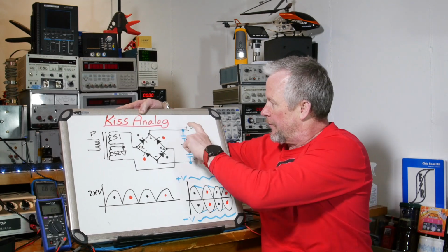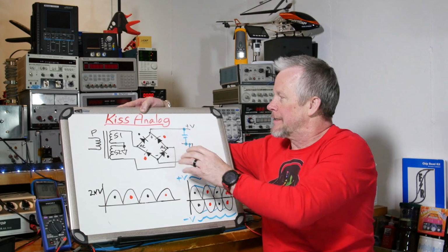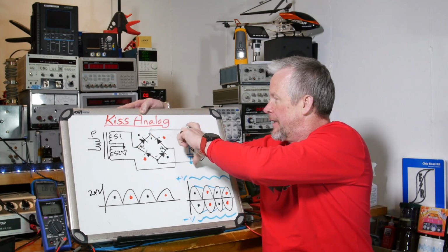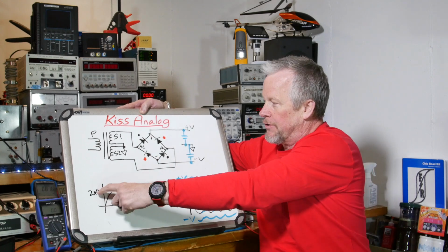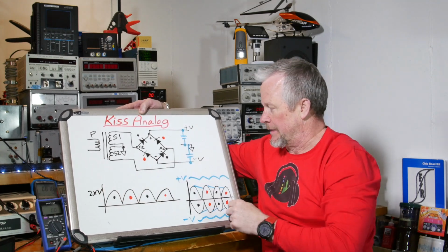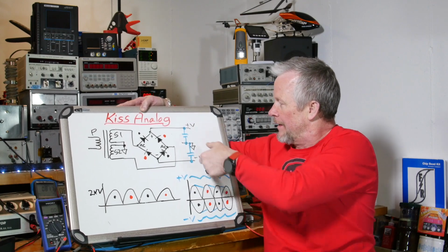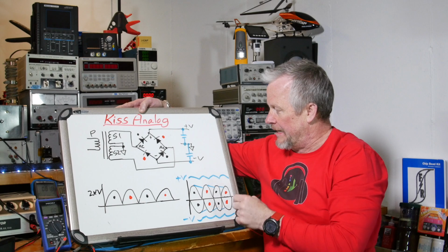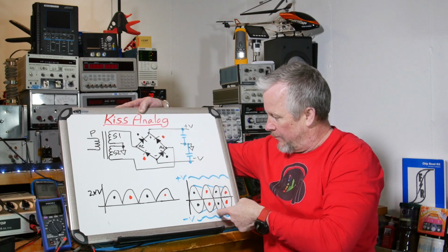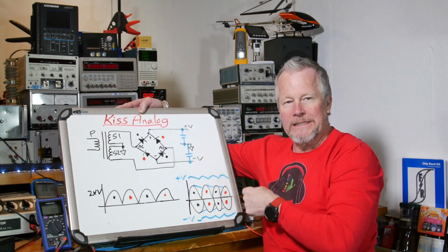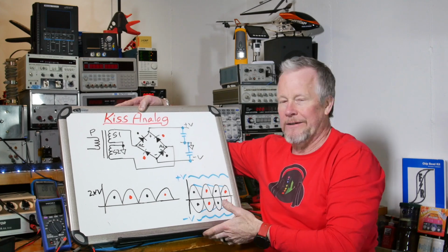And then the voltage over here, if you put your scope here, which you could because it's isolated, it's floating, you would see 2 times V, and you can see these pulses. But if you took two probes and put one here and one here, with the ground in the center on both, in one case you get the negative ones, and in the other you get the positive ones. That's just what it would look like.